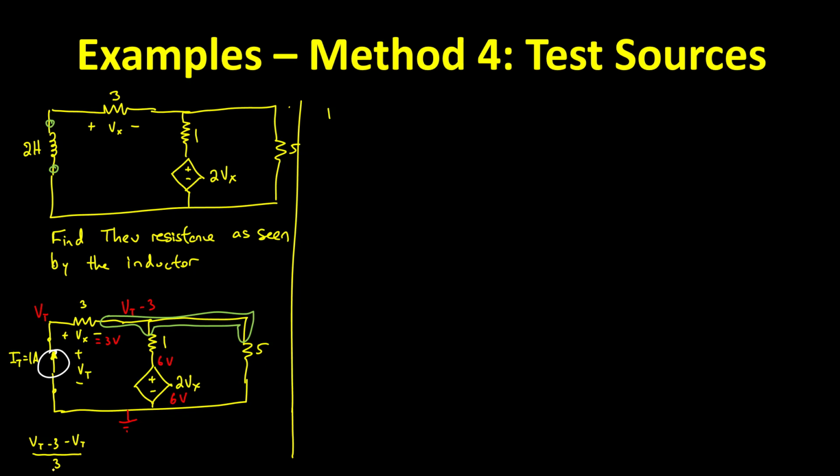And that should look kind of suspicious that it's -1, and that shouldn't surprise you because that's the current going to the left out of the resistor. But you could also have just seen it's -1 by saying there's 1 amp guaranteed to go into it from our test source. So let's just write that as -1. That's the current going to the left.